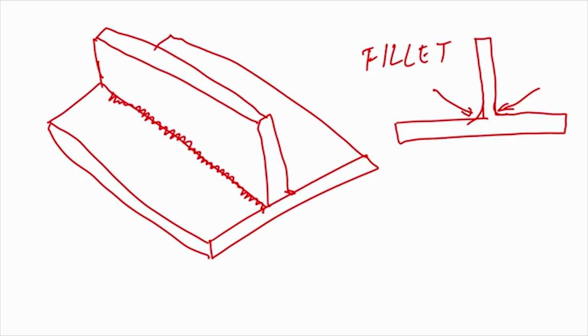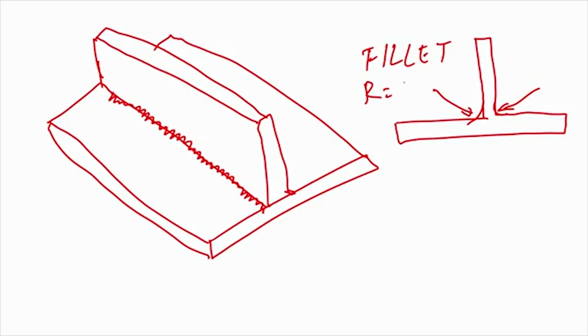Because of stress concentration, and because of limitations in fabrication, we need to add these two things. So, if I give a fillet radius equal to 5 millimeters, while this is say 10 millimeters and this is say 12 millimeters. Now, this is fairly complete, and this is where the instructions are very, very important.